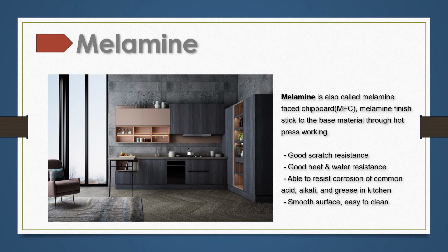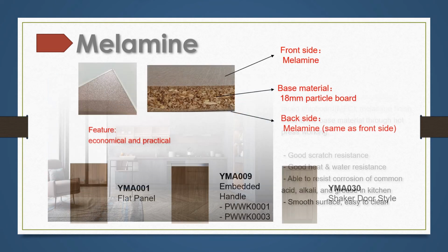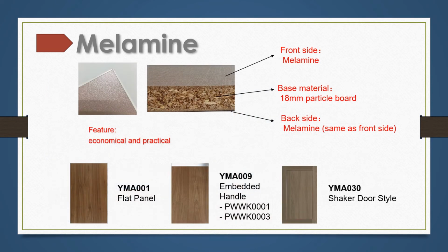Here is a list of preform finish: melamine, laminates, UV lacquer, acrylic, metal foils, and wood veneer. Melamine and laminates are the two most economical options among all door finishes. We will use them in most of our orders. All of the preform finishes here need edge bands.